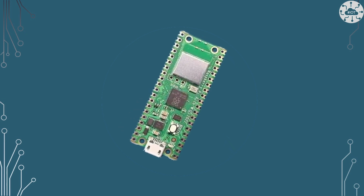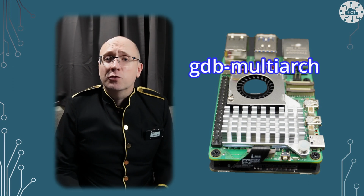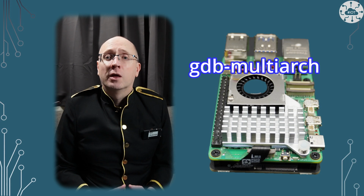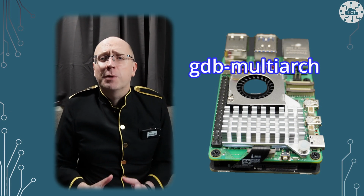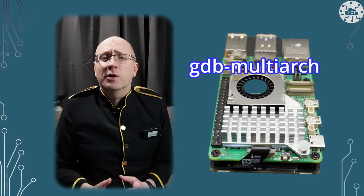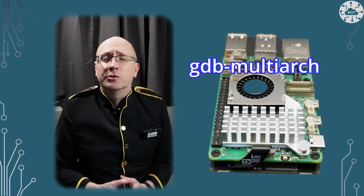I'd be really interested. Finally, if you're running the debugger on the Raspberry Pi, you should also use GDB multi-arch from now on. Most of the other platforms like Mac and Linux have already moved to this, so not surprised to see the Raspberry Pi follow suit.